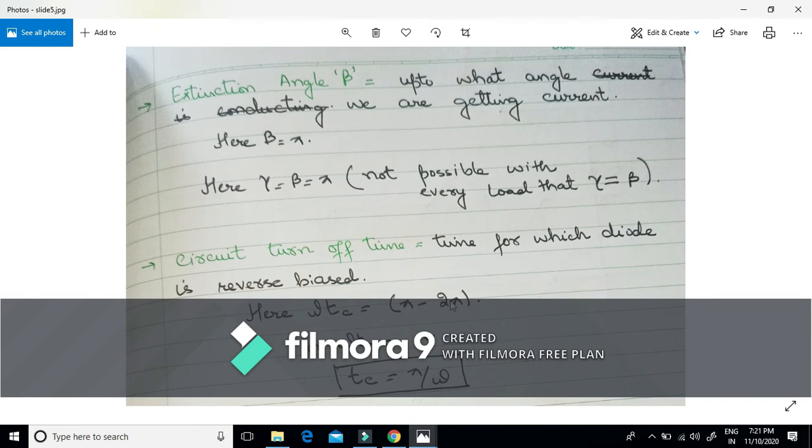This omega TC is not pi minus 2 pi, it is pi to 2 pi. That means omega TC is equal to 2 pi minus pi, that is equal to pi, and this is the period for which this diode is reverse biased, that means from pi to 2 pi. That time period is 2 pi minus pi, that is pi, or we can say TC is equal to pi by omega radians per second.